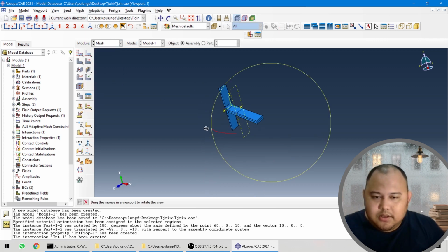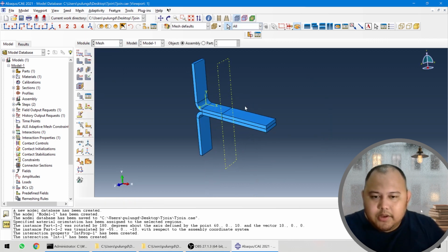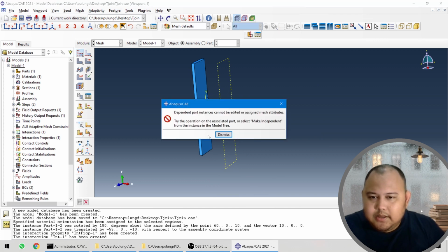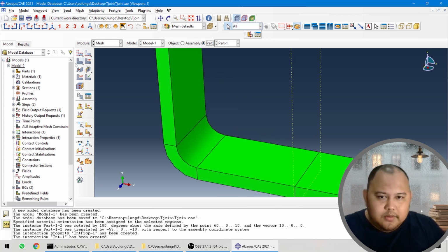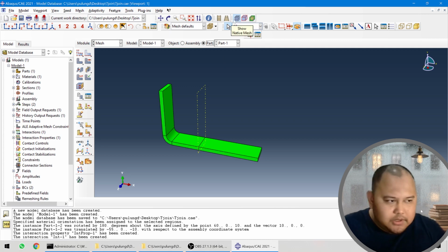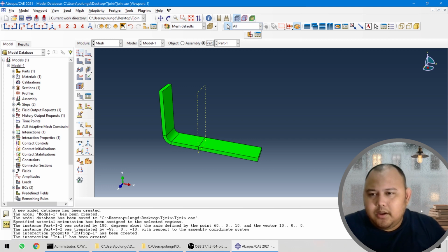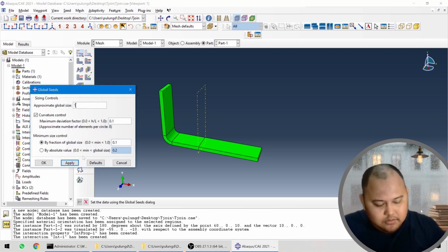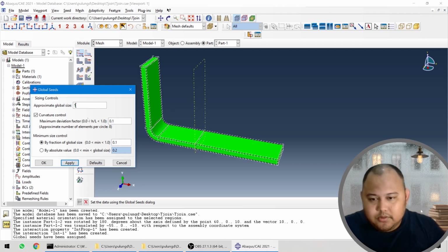Okay, and then we mesh. So how are you going to mesh it? Just basically here. So this is what I told you usually. If you're modeling composite at the coupon level, usually the mesh that is suitable for typical epoxy or typical composite should be around 1 millimeter. Okay, 1 millimeter. So yeah, this is good enough.